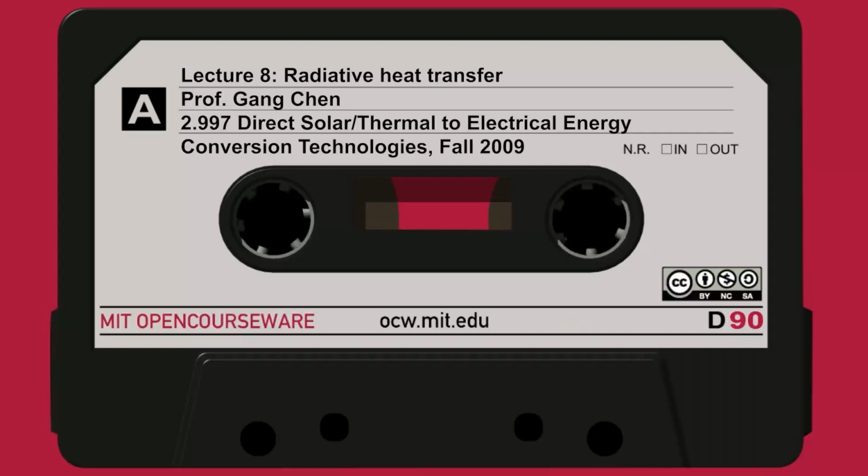If I integrate together all the energy going into the surface, but still at a certain wavelength interval, only at a certain wavelength, then I get a hemispherical. So that's over all directions, and spectral. And you can calculate from here to here. If you know this, you know everything.